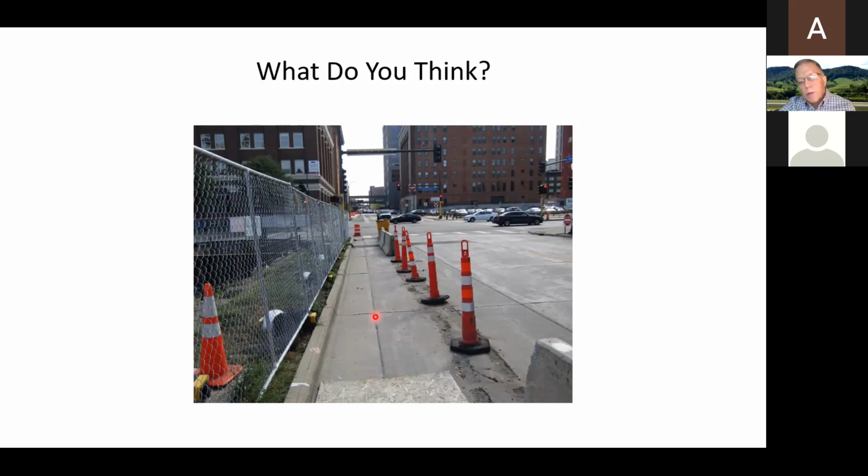I mean, of course, that happens during construction. But what bothers me is the way they left this. And maybe another flatbed's coming back in the morning with more materials. I don't know. But would we agree this is not a detectable situation right now with those tubular markers? So to me, at the very least, they should have tried to put in some channelizers in there. Maybe not crash worthy, but at least they would have been detectable. And you can see at the bottom here, part of the temporary ramp that gets people from the sidewalk to the street level.